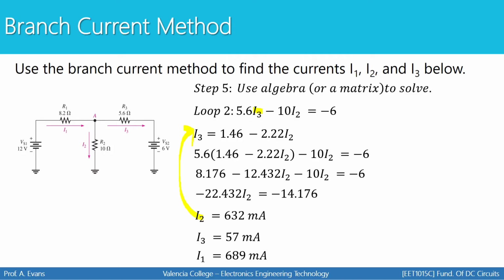Now, as you're doing these problems, if one of your currents comes out to be negative, that just means the direction you initially picked was incorrect and current is actually flowing the opposite direction from which you picked. It doesn't mean you have to change any of your calculations or go back and redo the problem and change the arrow. It just means you need to be aware that current flows in the opposite direction from which you originally identified it. You just have to keep that in mind if you're going to go forward with this problem and calculate other values like the voltages for each resistor.